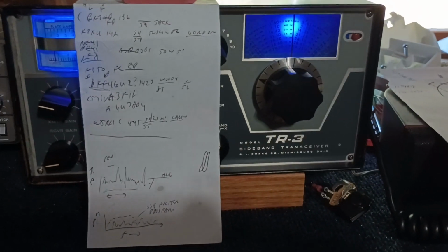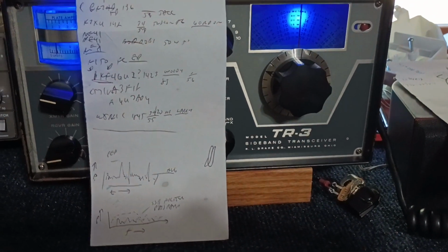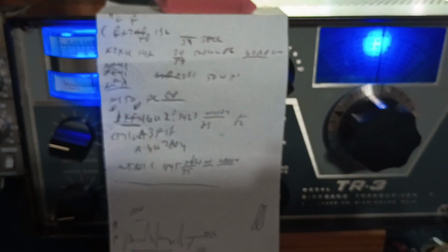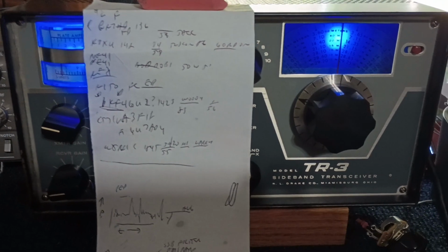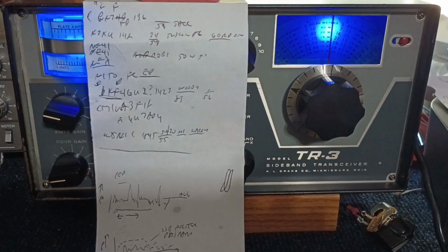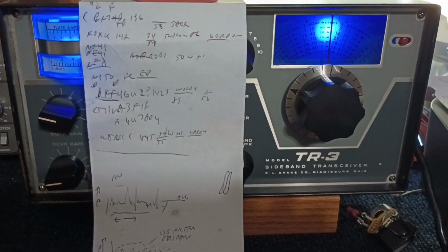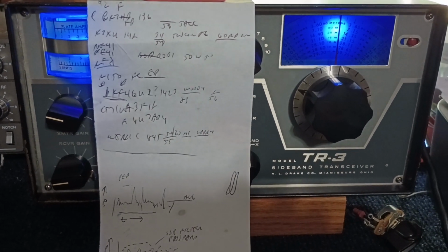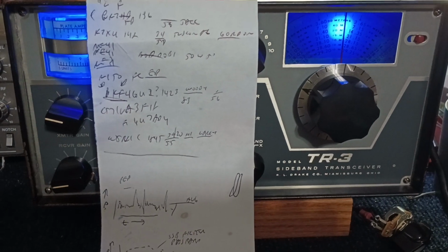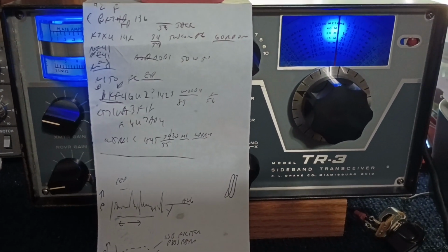This Drake TR3 has pretty much everything but speech processing, and I want to add it. That can be a fairly complicated design. The microphone amplifiers in that radio, TR3 and TR4 from the factory, were 5 kilohertz wide, which is horrible, since the sideband filter is only about 2 kc wide, and my experiments proved that having too wide a signal coming in actually distorts the shape of the sideband filter. It doesn't work nearly as well, and they're useless frequencies.